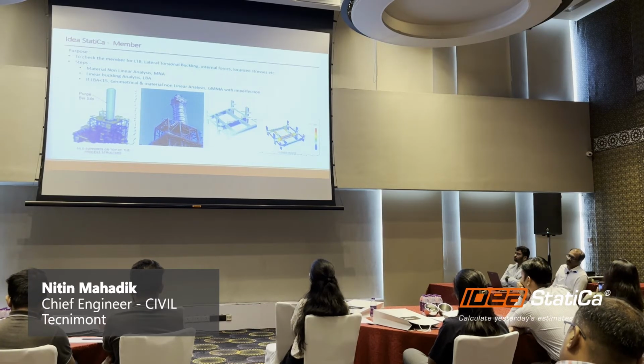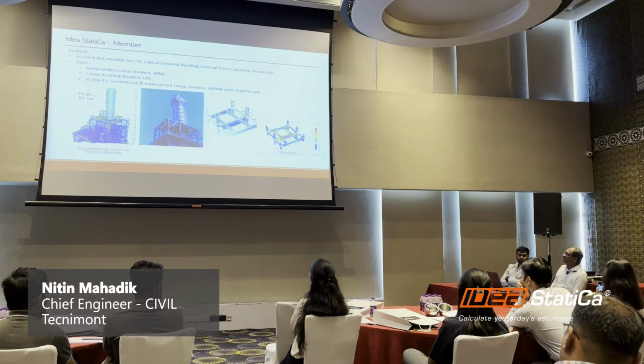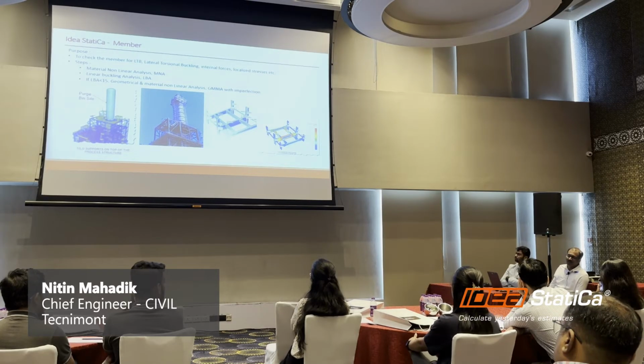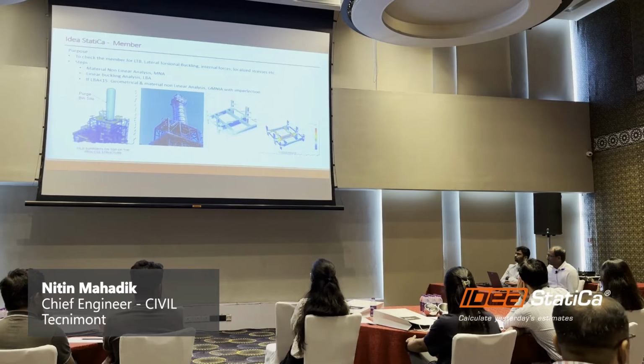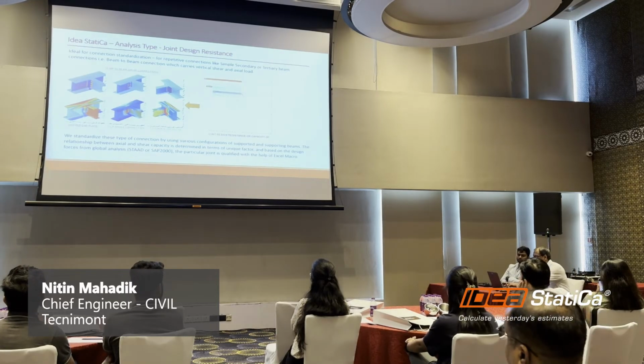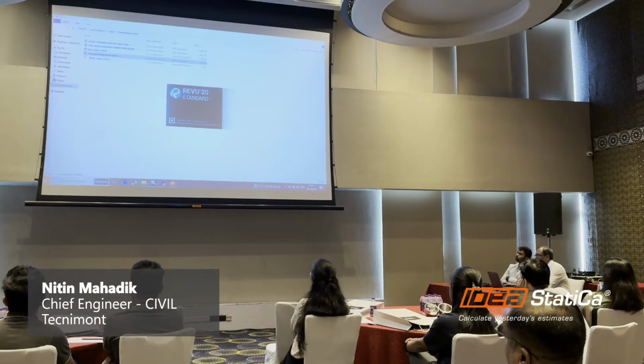And similarly, in the project which is going on in Tecnimont, in UAE, there are different demands from the client. For example, one client has asked us to prove that the LTB, meaning lateral torsional buckling, is properly implemented, or whether the plan bracing we are giving to break the length of the member is functional or not. So with IDEA StatiCa we used to prove this. So that is one help that IDEA StatiCa always gives. I will show you one example of how we prove the TQs from the clients.